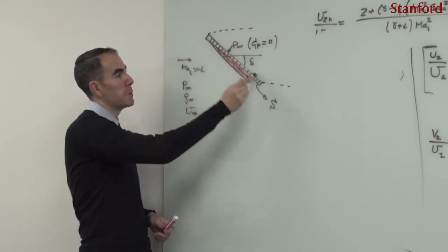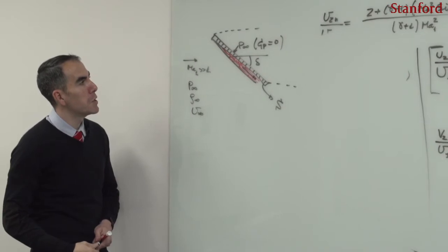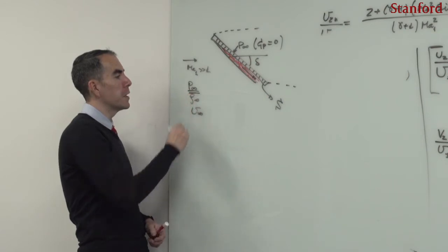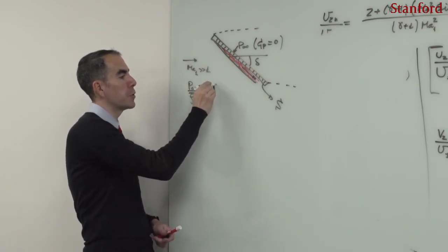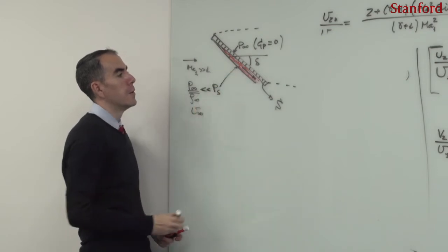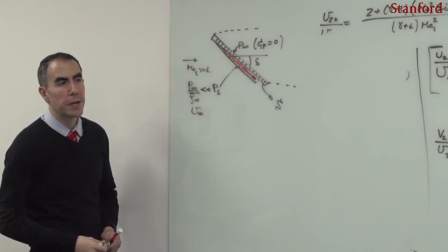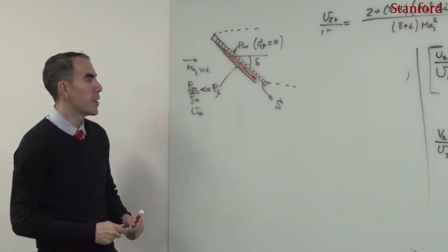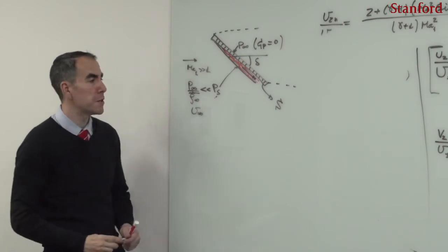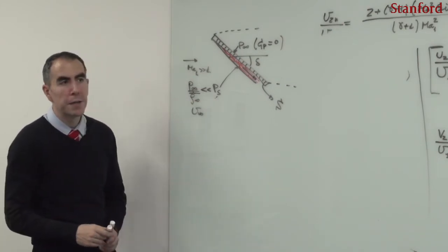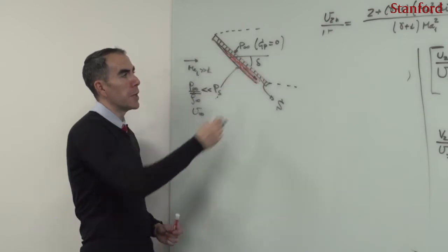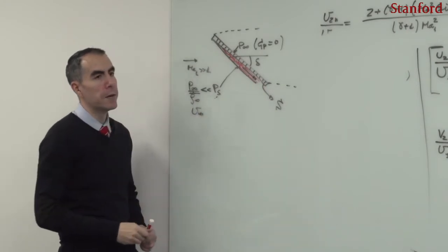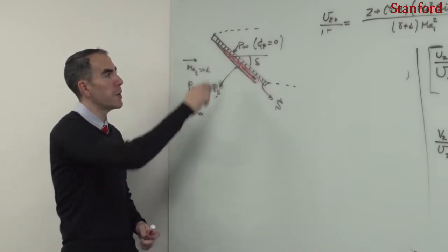Well, that's also an approximation of the theory, and it becomes accurate when this pressure P infinity is actually much smaller than the pressure that develops on the surface of the plate. For instance, if these two pressures are more or less similar, as in subsonic aerodynamics, where they differ only by amounts much smaller than the static pressure at infinity, then this assumption becomes really bad. But remember that most of the wave drag on an object flying hypersonically is caused by the front surface.